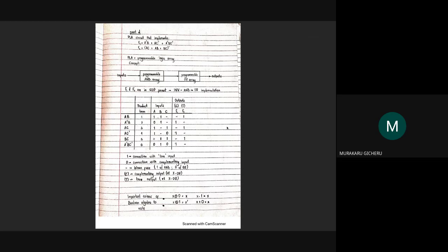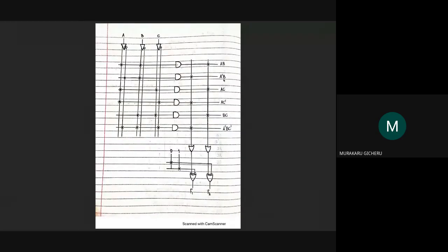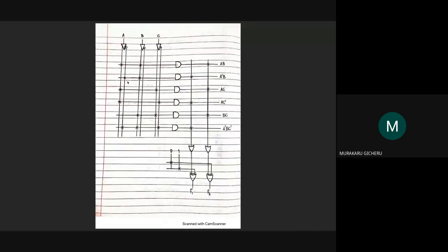And for not A B, we will connect not A and B, and the others will be blown. Because in the table, this is what I mean when I say 0 and 1. This not A has been denoted as a 0 on the table, which means that I'm going to keep the fuse from the complementary equivalent of A intact, and I'll get rid of all the others. So this is not A B going through the AND gate here.